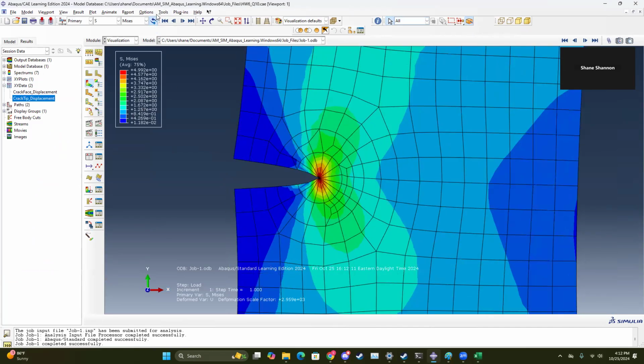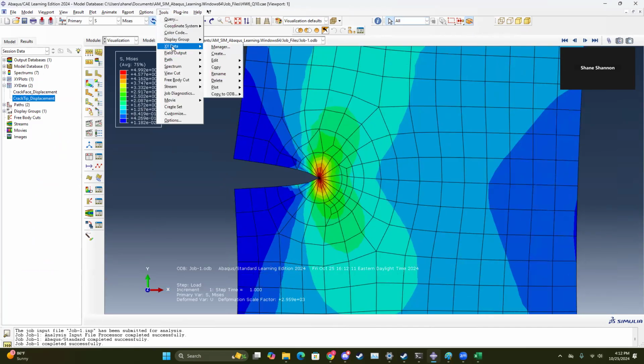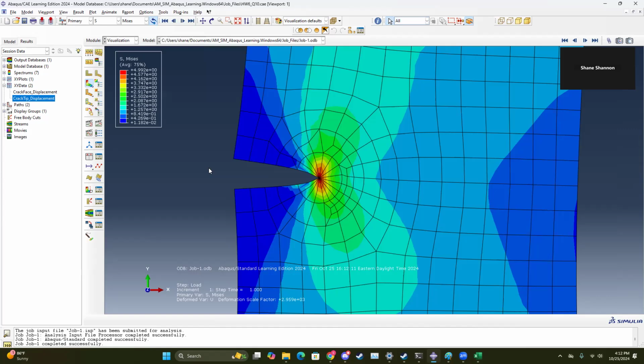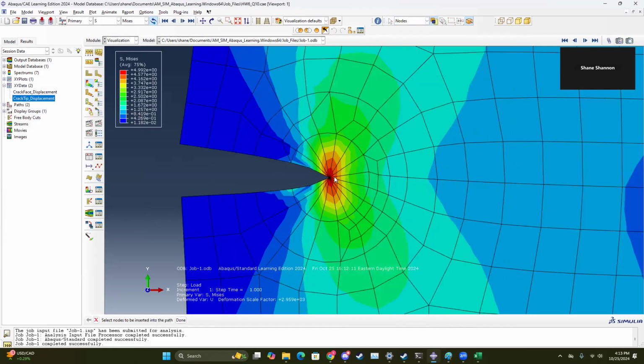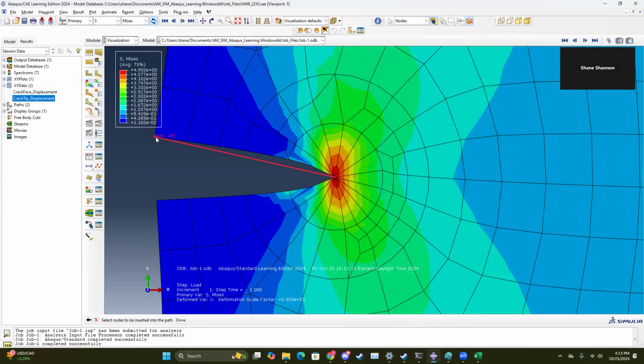And when doing the X and Y, like I mentioned earlier, it's kind of hard in the previous one because it's not separated. What I did that kind of works is, while it's in this deformed shape, you go through path. Path using the node list rather than edge, because it freaks out a little bit when doing the edge case. After the crack tip, do the edge.